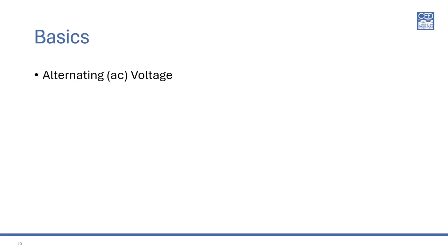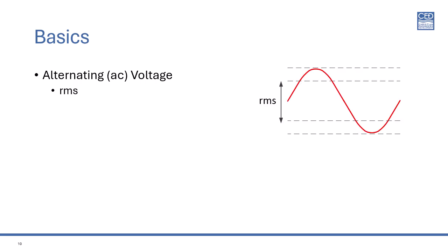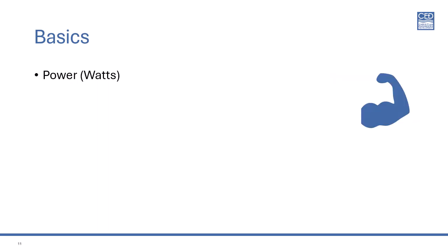The electrical voltage is available in either AC or DC, where AC, alternating current, is normally referred to as the RMS voltage. This is the value of the highest useful power, but it has a peak-to-peak voltage which is significantly higher, and this will affect the safety aspects of the design. Coming back to power again, and from Ohm's law, power is voltage multiplied by current, or voltage squared divided by the resistance, or the current squared multiplied by the resistance.